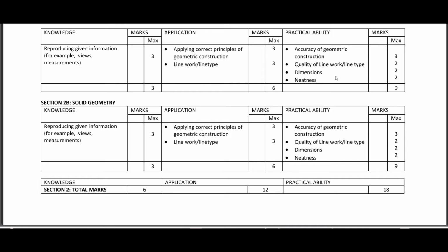I have to say this because I see this very often, that people will not dimension their drawing. So once it's a circular object, say for example it's an ellipse, dimension the major and the minor axis if you're doing rectangle method, so the horizontal and vertical. If you're using, say, concentric circle method, the diameter of the circle that represents the major axis and the minor axis. If you're doing, say, a cycloid, same thing, you're measuring the wheel or the circle, the diameter of it, as well as the horizontal, which is basically representing the perimeter of the circle. Alright, so that is that.